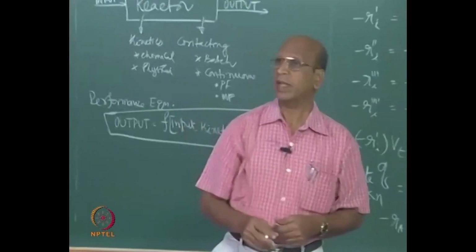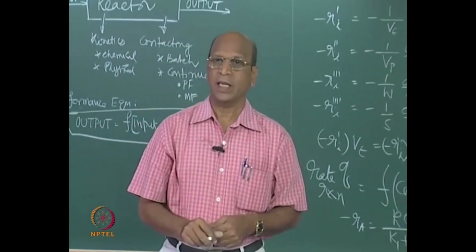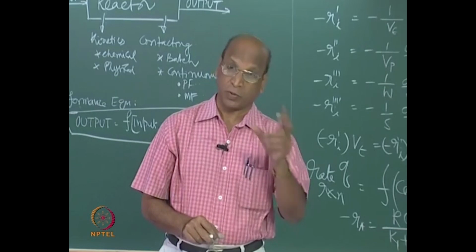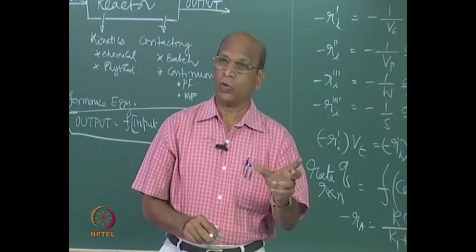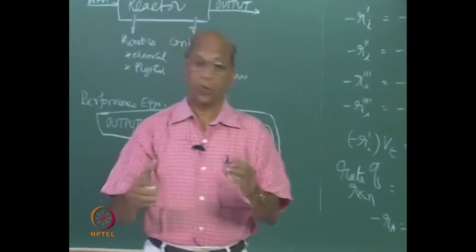Okay, and I think one answer was there, what he told. Rahul, what you said, that one point is right. If the reaction rates are very slow, then we will go to batch systems. The reason is, it is not the volume and all that. You can give whatever amount of time that is required in a batch system.